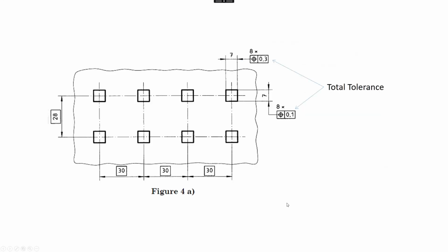Right, so we've got some tolerance zones here. In this case, they're not diameters. And what this is showing basically is we can use different tolerances in one direction to the other direction. There's differences where these boxes are positioned. If the box is positioned on the end of the arrow of the feature, what it means is the center line of the feature rather than the face. So that's quite an important observation, and we'll go into that in more detail shortly.